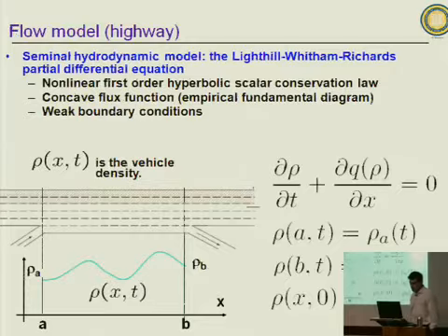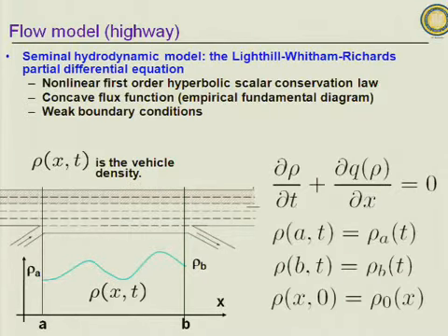So for this, we need to use mathematical models which are distributed in nature, and I think that's clear from both applications: these 1,000 kilometers of water channels, or this network of highways. In the specific case of the highway, first-order models, which are first-order hyperbolic conservation models, are a very good approximation of flow and traffic.